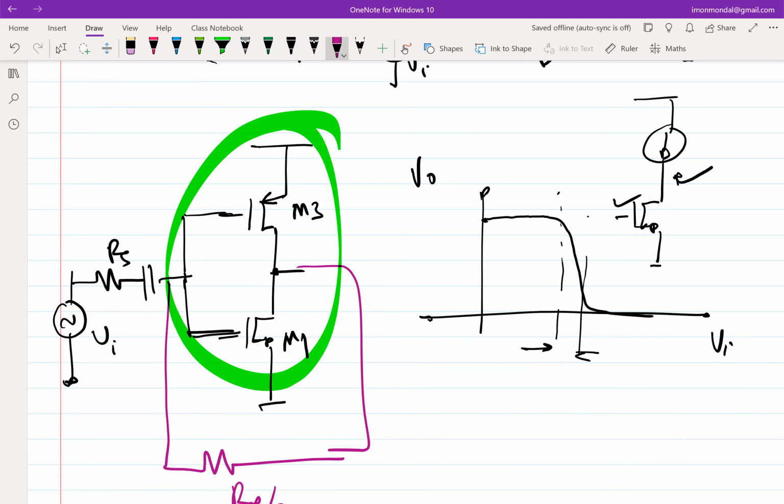So what is the gain here? If you assume GDS equal GDSN equal to GDSP and GMN equal to GMP, in case of an inverter, what is this slope? Assume it to be a straight line for convenience. The slope is GMP plus GMN divided by GDS, and if they are equal, it becomes GM by GDS. That is the gain. So what is the gain of this configuration? It will be GM by GDS, so the slope doesn't change, and essentially this part will be a superimposition.